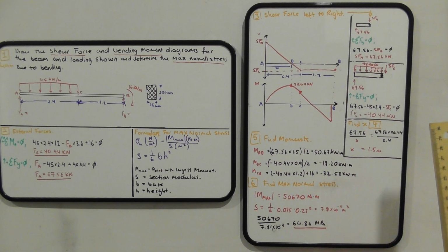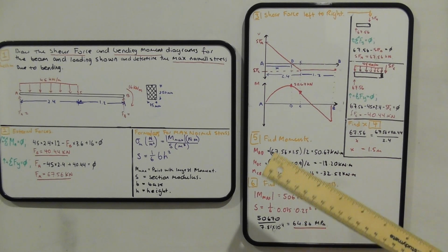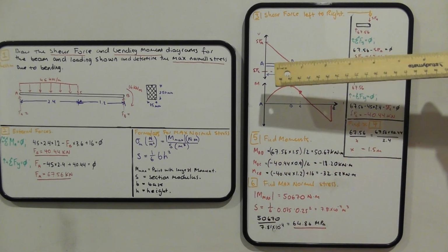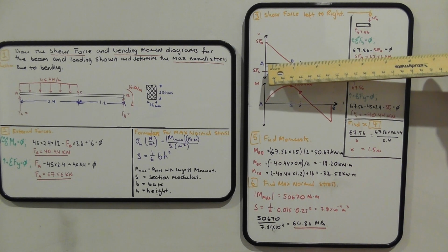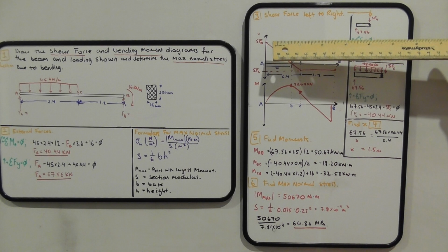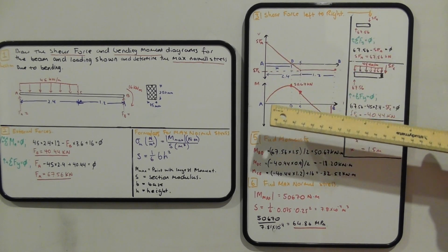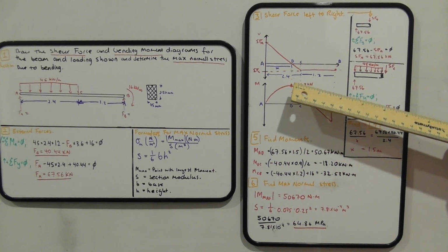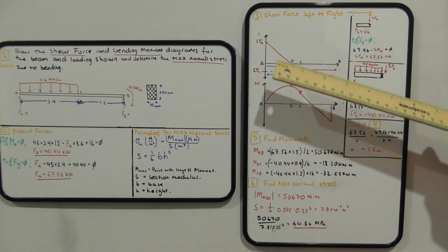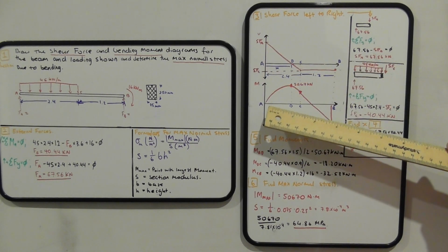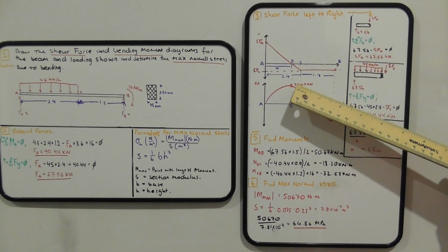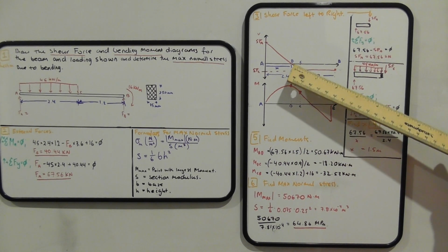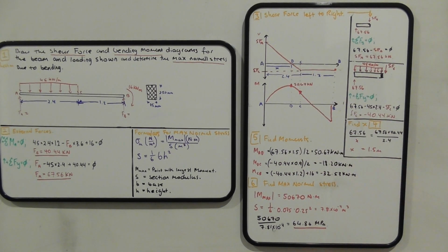So then if you were to draw the moment diagram, you look at the shear force, and if it is going up on the triangle, that means the slope is going up. As it's going up, you have a slope, and at that point D, you will actually find that's the maximum moment.